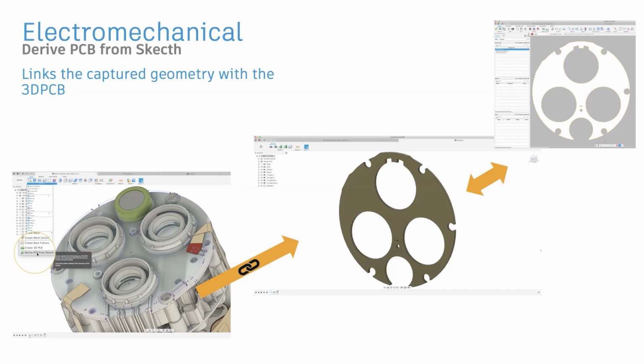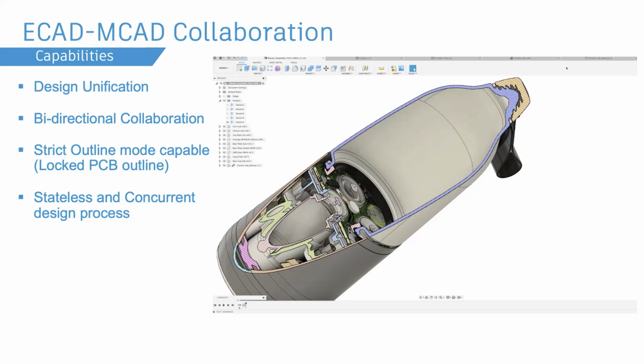Now here, as the name says, it's from Sketch. So this will only work with a sketch body. It does not work with surfaces like Create 3D PCB can, which I truly recommend that you use sketch profiles anyway. Now, let's summarize what we've come to.